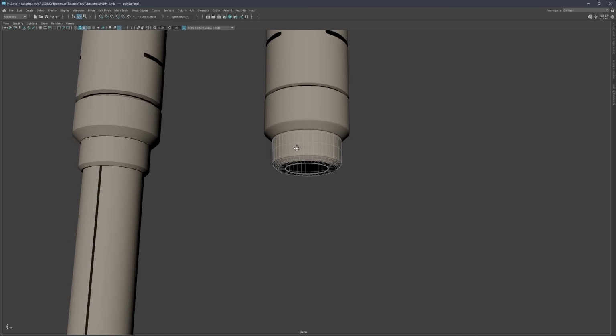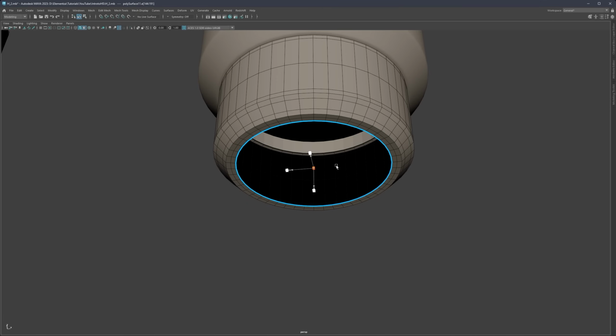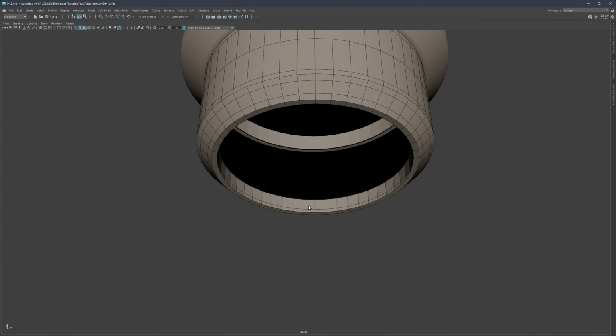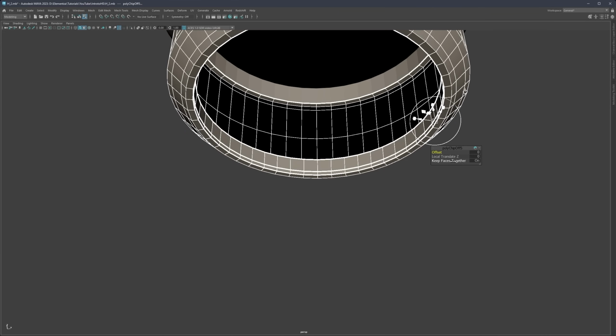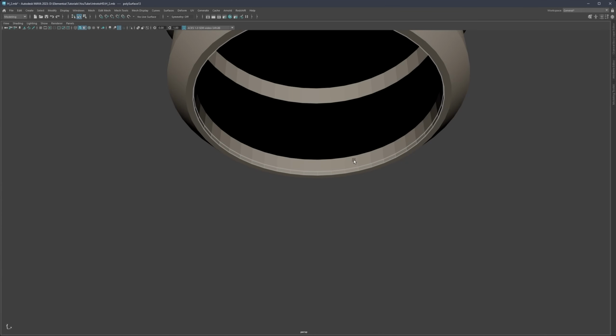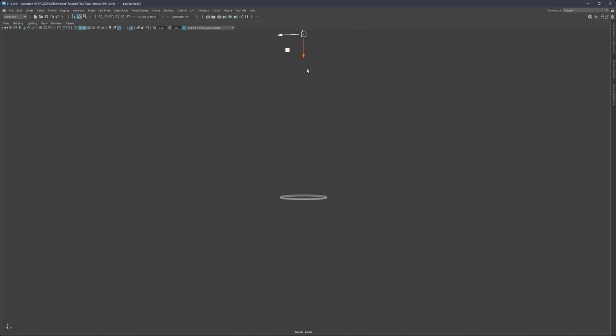All right. Now we're going to need to repeat the process. And let's now maybe scale this till here. And actually, you know what? Let's go to face and then delete this and push this up and add one cut here. And now we can do it a bit differently. Let's say we take this and duplicate face, Q to confirm, and we can now borrow this part. And now the pivot is all the way up. If you select this part, you're going to see where the pivot is. Again, just hit D, right click, reset pivot, and then it's going to snap into its place. Hit D to confirm.